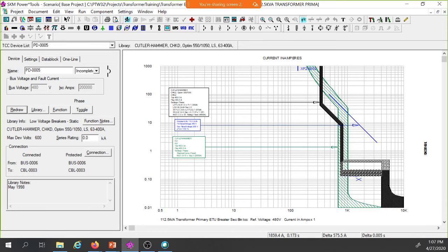I can move this short time delay up or down, and you'll notice if I put it on its lowest setting, which we ship these things at their lowest setting. And you know what happens? When we ship these, people don't set them in the field, and this breaker could trip on inrush, because the inrush current's right here in this short time delay. It can trip anywhere in between this time band, and then if you're not smart enough, you may not realize that you need to make an adjustment, and you shouldn't just make that adjustment on the fly.